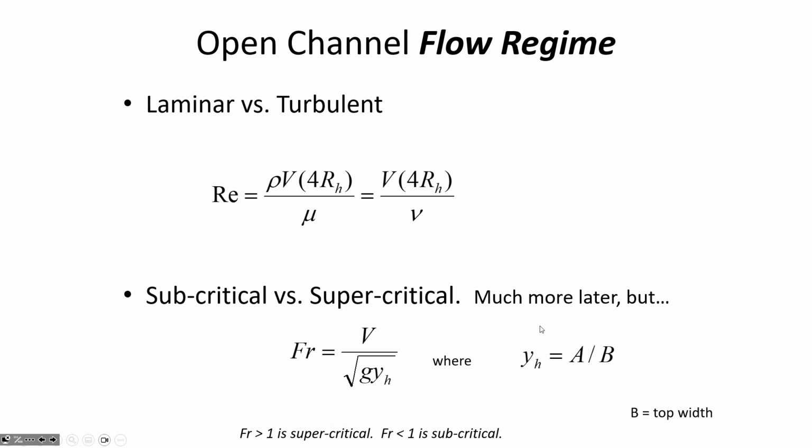Here, the hydraulic depth, Y sub h, is the cross-sectional area divided by the top width. So if you've got a rectangular channel, the top width and the bottom width are the same. That's no big deal. But if you have a trapezoidal channel, just keep in mind that the bottom width and the top width are different.